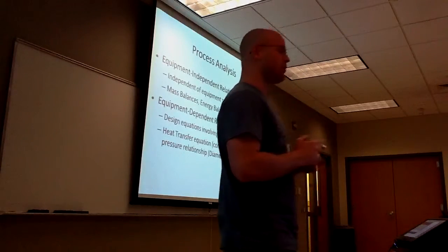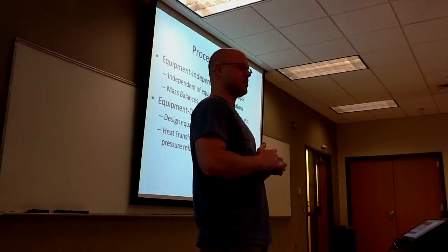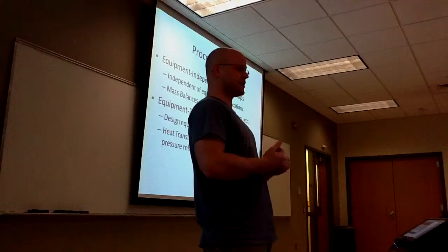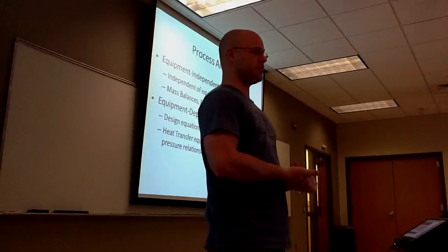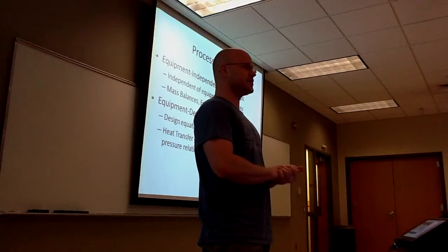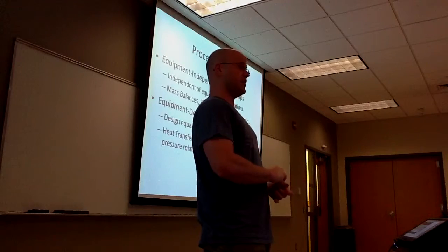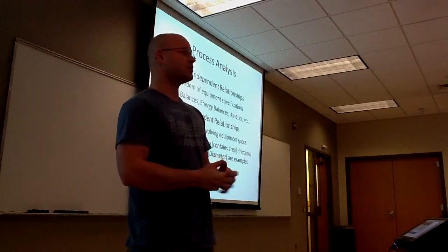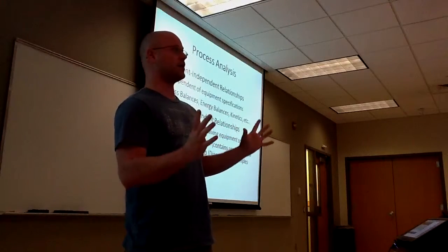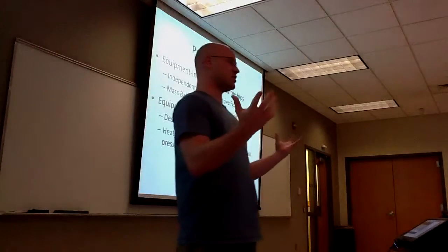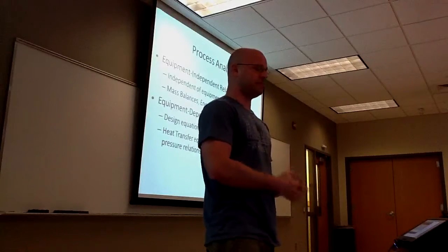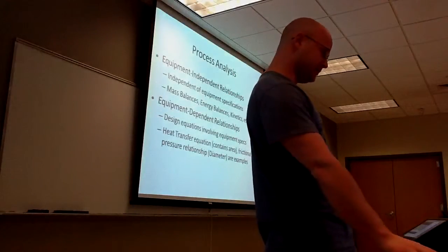There are equipment-independent relationships, which are independent of equipment specs, such as your mass balances, energy balances, and kinetics. And then you also have equipment-dependent relationships, such as your heat transfer equation, which depends on the area of heat transfer, or the frictional pressure relationship, which depends on the diameter of pipes. So these are the things to keep in mind.